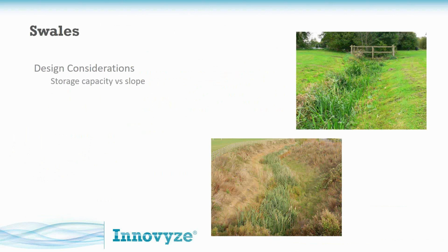Design considerations. Well, again, if most of these facilities run along a slope, you can't just go, all right, my swale's 3 feet deep with a 1 to 3 side slope. There's my volume. No, it's not going to fill up like that, right? If it runs down a slope, only the very end of it will really pond up. Something to keep in mind. Storage capacity versus space, right? So again, if you have a volume requirement, you might need to make your facility bigger, maybe make it shorter at the top and deeper at the end. That's another way to really balance the true volume storage.